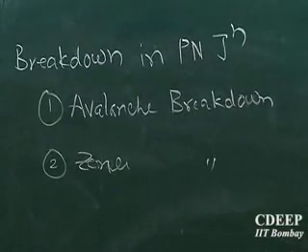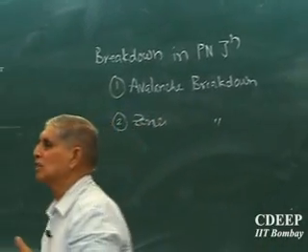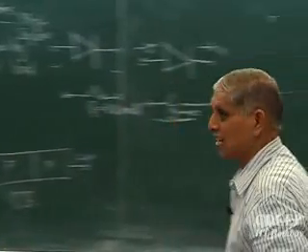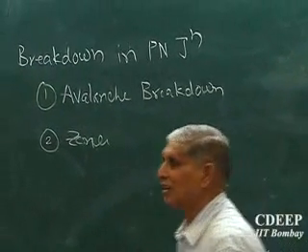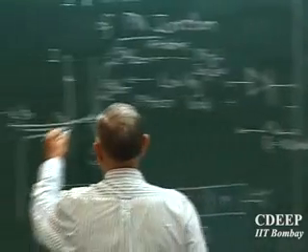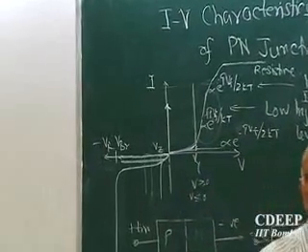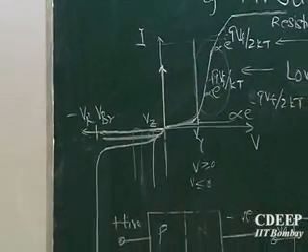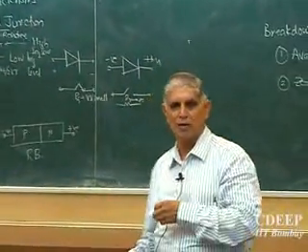However, in your lab, I hope you have already used a Zener diode. In many circuits they have Zener breakdowns of 5 volts, 8 volts, 10 volts. They actually say 8 volt Zener. So actually those Zeners do not follow the Zener breakdown mechanism at all. Typically, I can adjust my breakdown somewhere here, which does not follow the mechanism of Zener. But the values are comparatively smaller, 5 volt, 6 volt, 10 volt, 8 volt, whatever value, these values are available to us in markets.